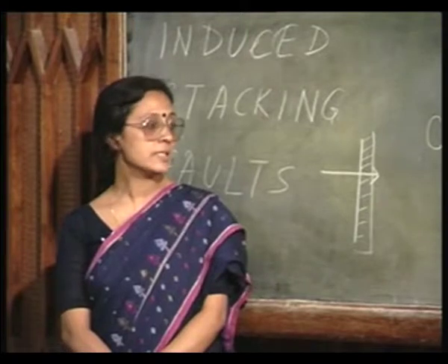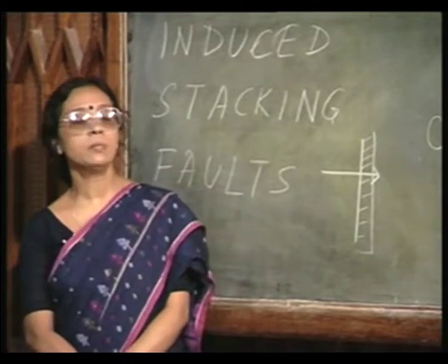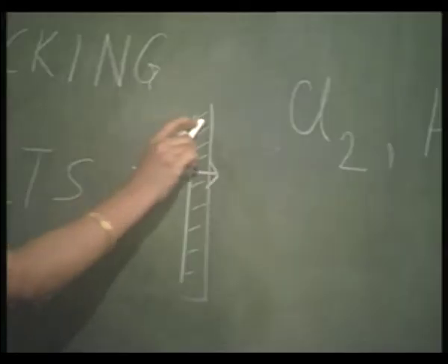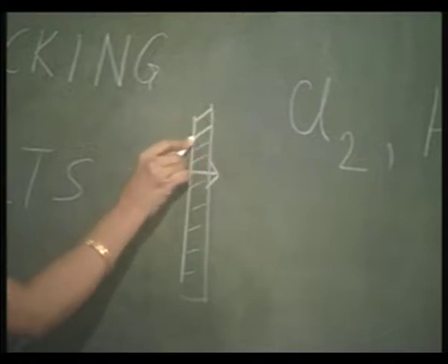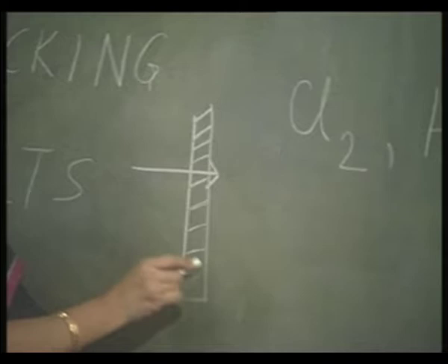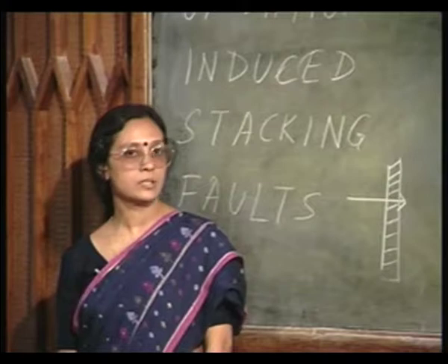Now, these silicon-silicon bonds are breaking and new bonds are forming between silicon and oxygen. But since this interface is the last region to be oxidized, there is a possibility that even though the silicon-silicon bonds are broken, they still have not found time to react with the oxygen to form new bonds with oxygen.